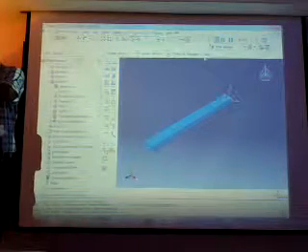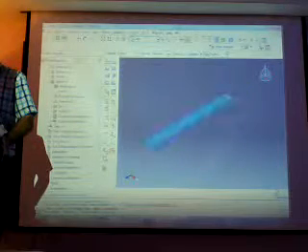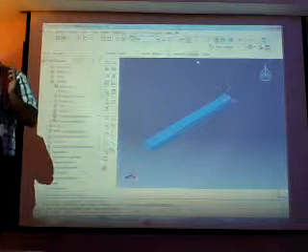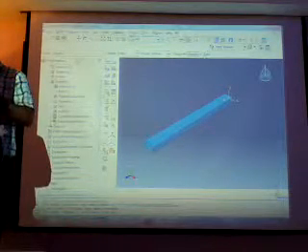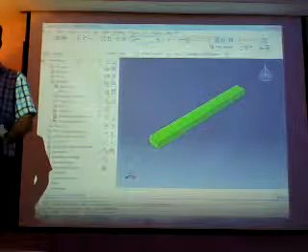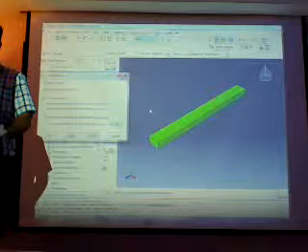Now I need to take here part. You can see part, assembly. For assembly, that's impossible because I take in the assembly part as a mesh on part. So here also I need to take part. I take part and seed the part, approximate global size. That's your mesh size.